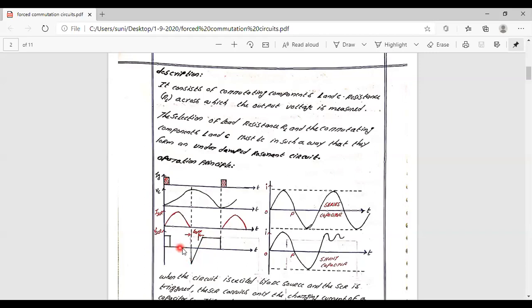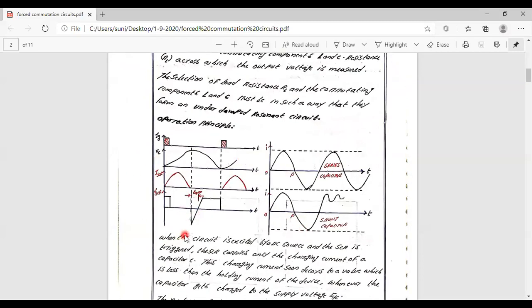Here from this point to this point, you have a zero voltage, isn't it? So that means the conducting instant is from this point to this point. As we are neglecting the on-state voltage drop, we simply represent the zero waveform. If we consider the on-state voltage drop, a magnitude of 0.5 volts is represented here. Okay, so that is for a class A commutation.